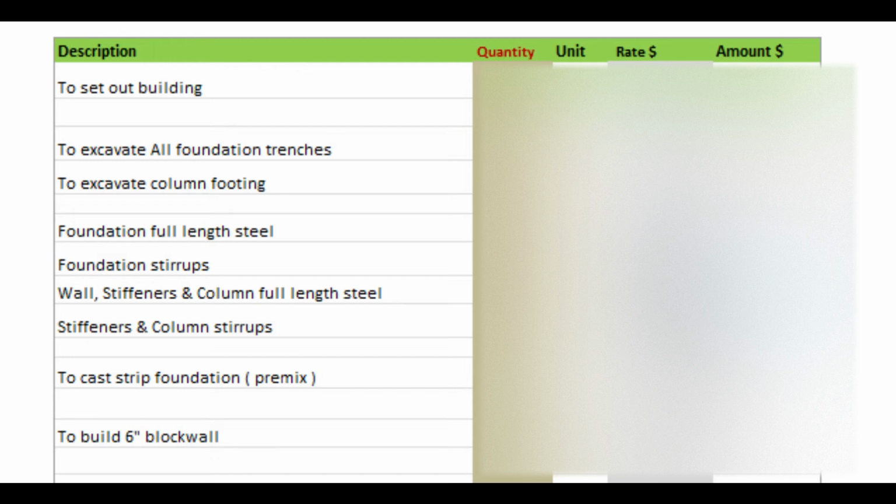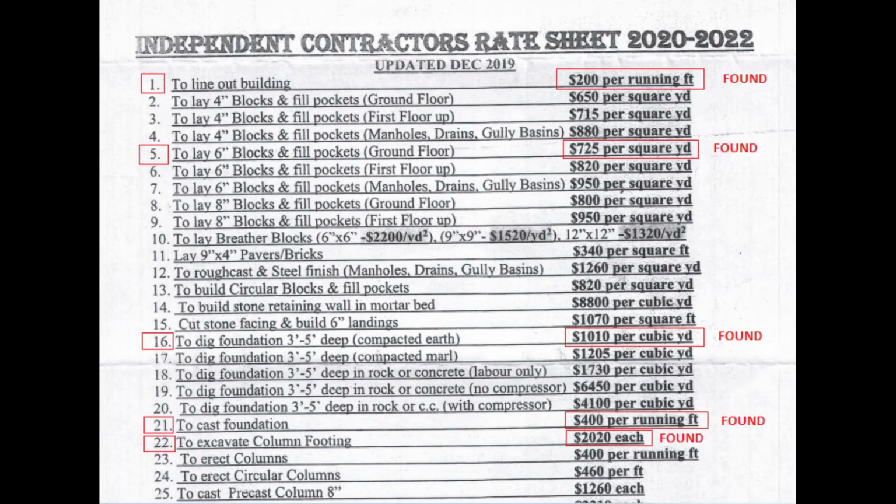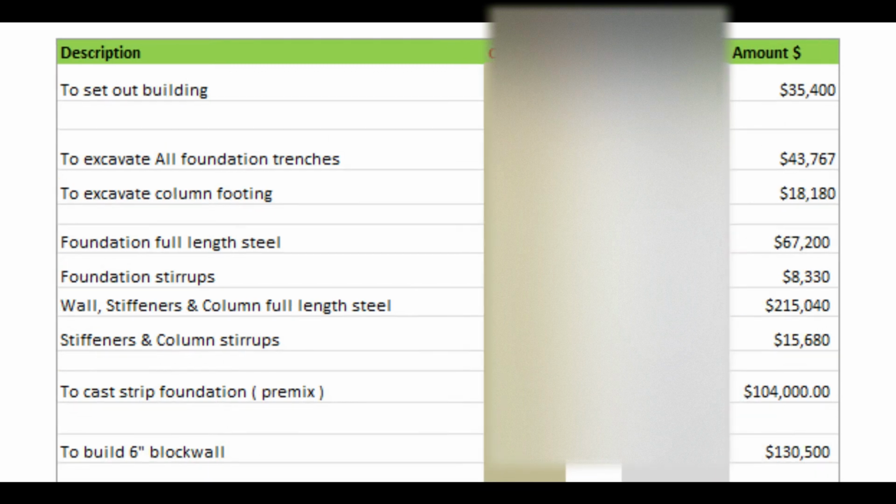The next thing that we are going to be changing is the block work. Originally, we were using block work as each per one. In this case, it is saying square yard. Now it takes 10 blocks to fill the equivalent of a square yard. An easy conversion is just to divide the amount of blocks that we had by 10, and then we can get the equivalent in square yards. So it's just dividing this by 10, and now we have the block work in square yard, which is aligning itself with the rate. And then we're going to rename the units from each to square yard.